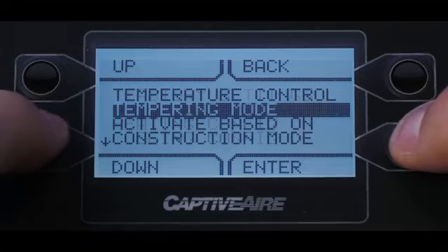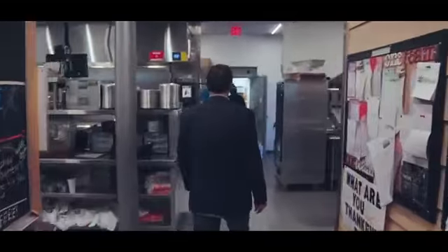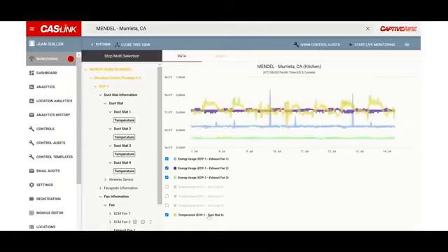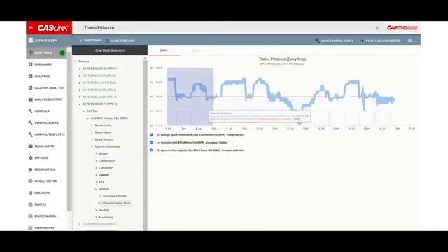There is no guarantee that the equipment will operate as it was intended to once you pass it on to the end user. If at some point settings are changed or something was not set up properly right after the building was turned over, then there's a risk that those units will potentially operate 24/7, operate at times where there's no one in the building. So a building management system takes away those risks. It gives you visibility of what your different components are doing and making sure that they are not only operating efficiently, but also operating only at the times that they need to be working.